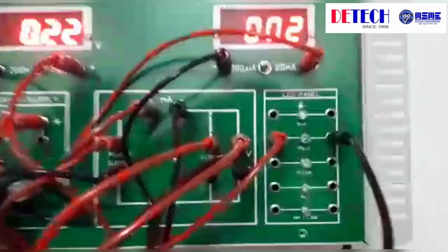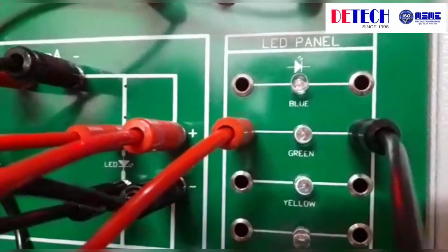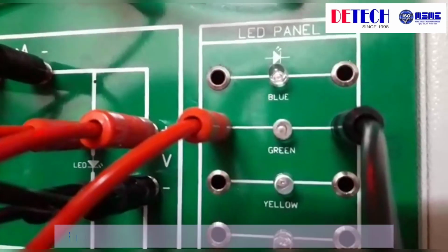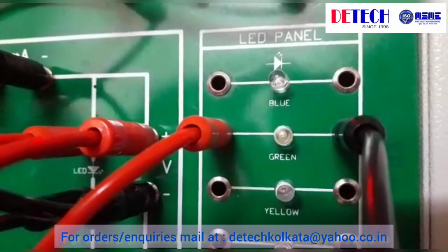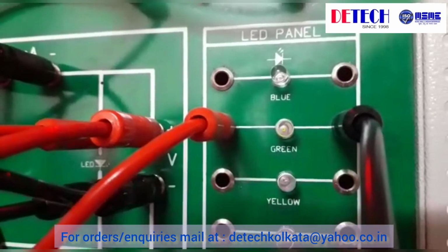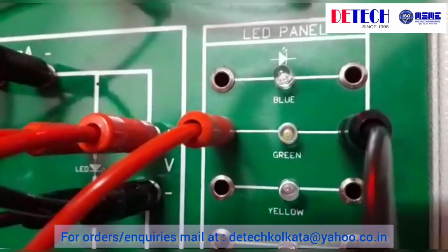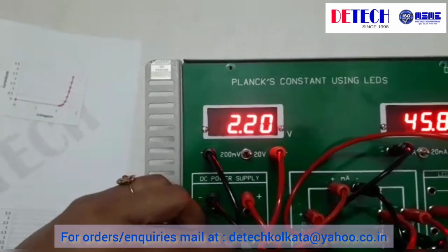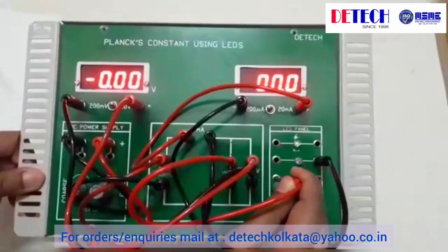Again zoom into the green one and we will see what is the voltage when the LED just starts to glow. It has just started to glow. So the current, 1 second, yeah, it's glowing, right? Yeah. So the voltage is around 2.20 volt. Current is 45 microampere. And for the yellow LED,